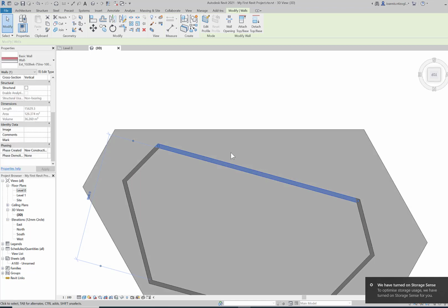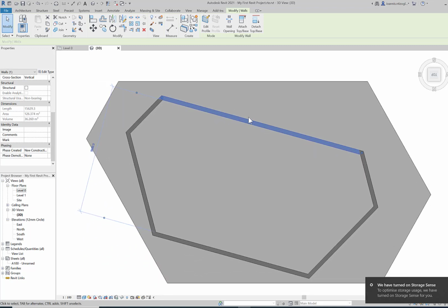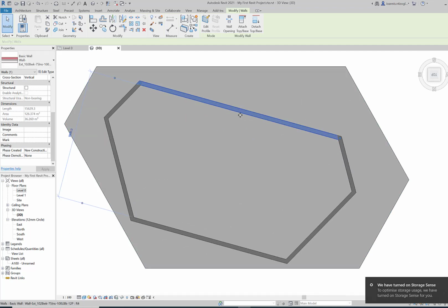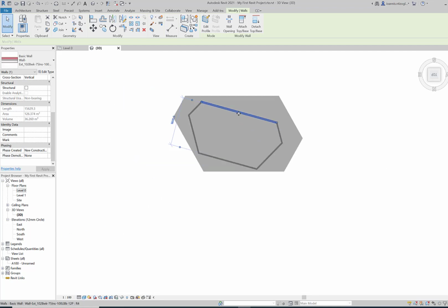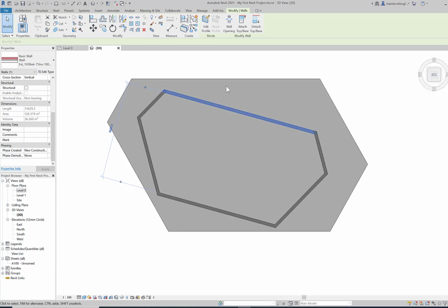Now I'm going to use a new tool, which is on your mouse. Your mouse has a little wheel in the middle, so if you click and drag the wheel, you will be able to relocate your view. If I use the wheel upwards or downwards, I can zoom in and zoom out. Okay, the next thing we need to do is add some rooms.